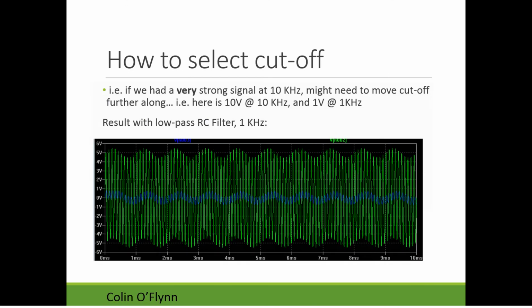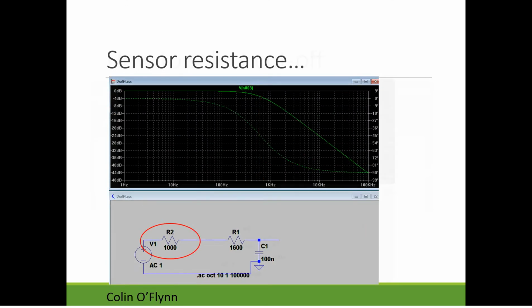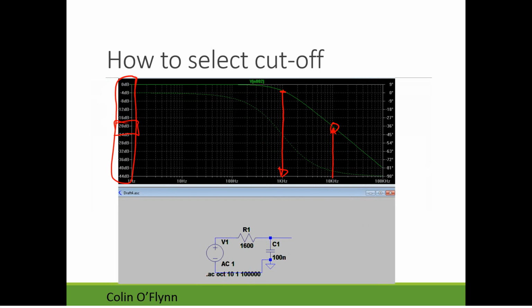So what you might need to do, going back to our filter design, is shift the cutoff frequency even lower. So what we might say is that we're going to shift it such that it starts to roll off like this instead. So we're going to roll it off at 500 hertz or whatever that frequency is there, or like 200 hertz. It looks like I picked randomly.